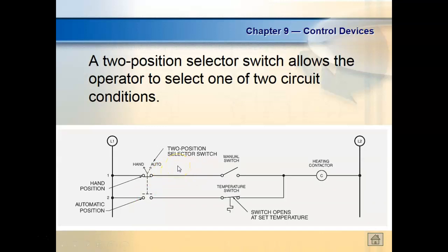The legend plate basically tells what it does in the application that it's running in. The legend plate is replaceable. So I could have two exactly the same selector switches doing two different tasks, right? You understand? But each one of them will have the label for the application that they're doing. A legend plate, excuse me.